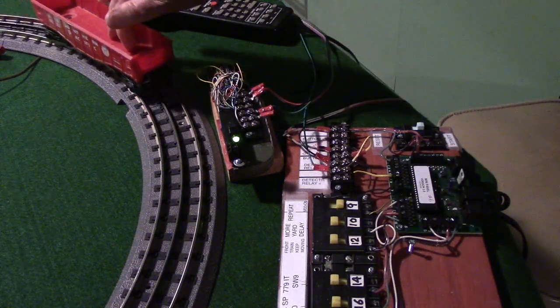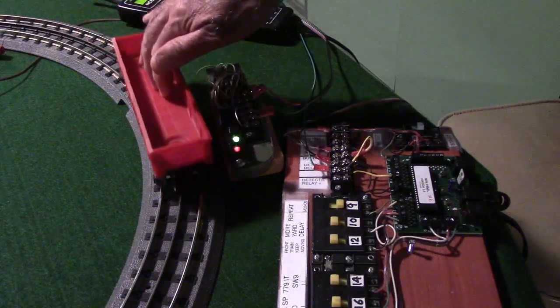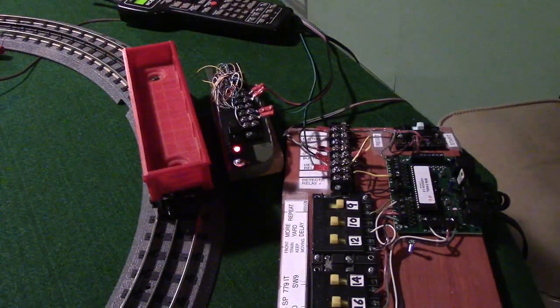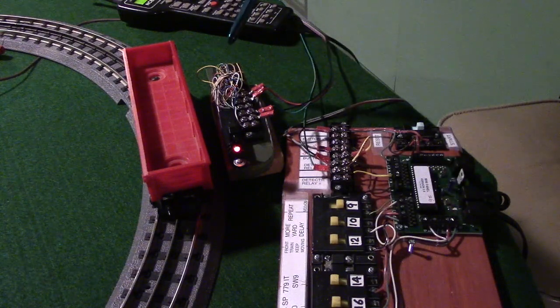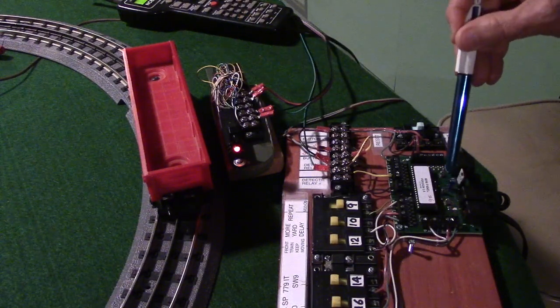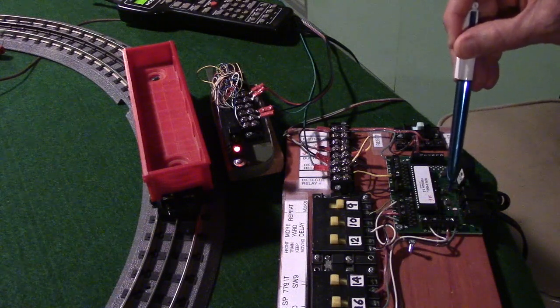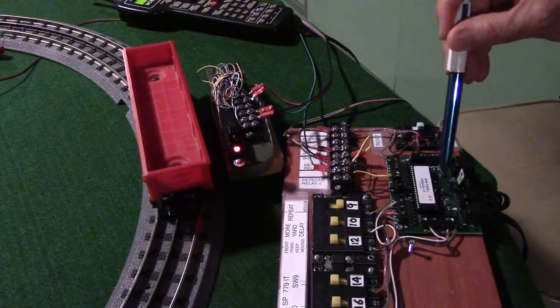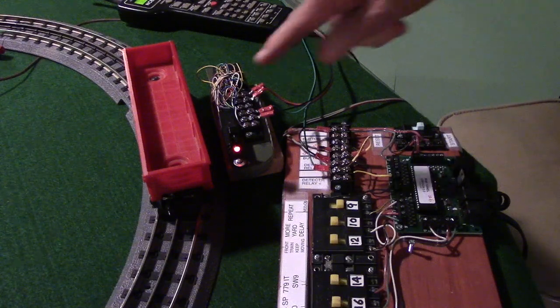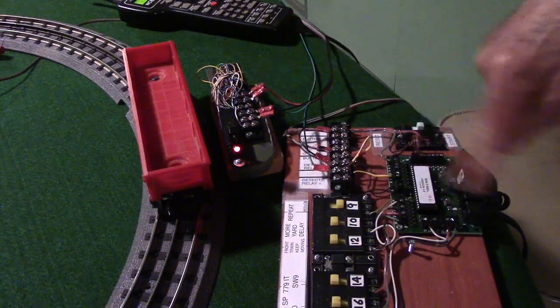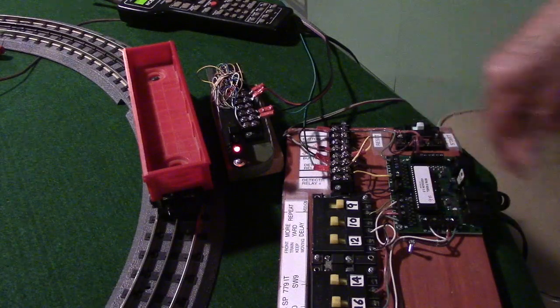If the detector relay closes, we have our program set up so it'll sense that. You see how that went to red, which closed the relay, and this thing detects that, and it adds an extra delay. You can see it's still blinking, but it's slowed down quite a bit. And that basically tells us that this detector is communicating with our programmable train controller, the mini panel.